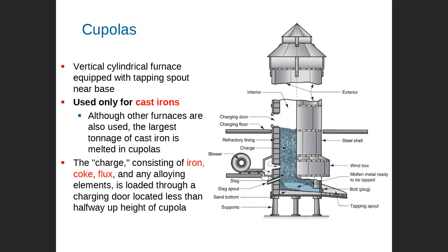And then we pump hot gases here, very hot gases. Then the coke starts firing, and the temperature increases up to the melting temperature of the iron. Then the iron melts and becomes liquid, and we trap the liquid here. The flux or slag is taken from this side. After the slag is created, it is removed from here, and the liquid is removed from here.